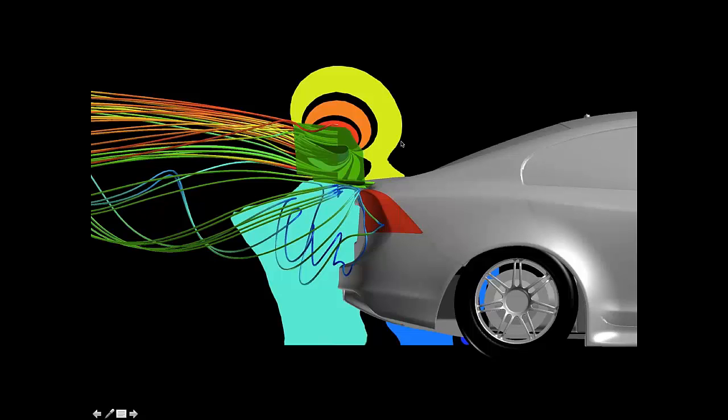So here's an example of a few streamlines and pressure contours that you see on the car. So you're dealing with quite a tricky region of the car. As your airflow's thrown out of the way at the front, it converges at the rear. So there's a lot going on in terms of trying to control the airflow, especially with end plate mounted wing. You can see it's quite turbulent around the tail light region there. On the top of the wing there you've got your high pressure build up, and then underneath the flow accelerates and you've got your low pressure there.